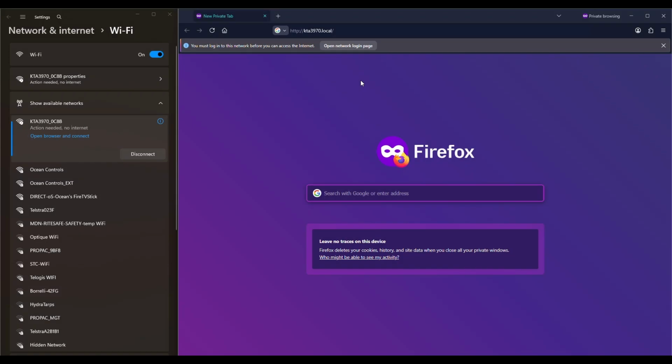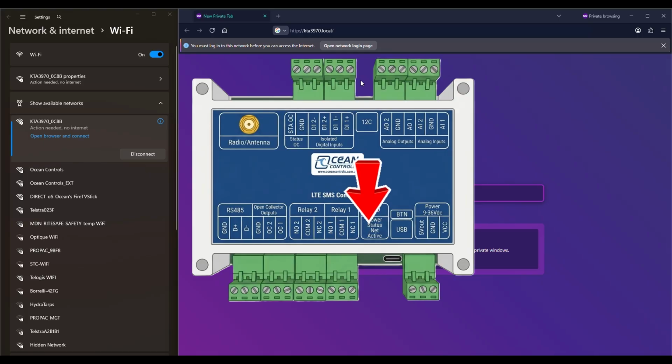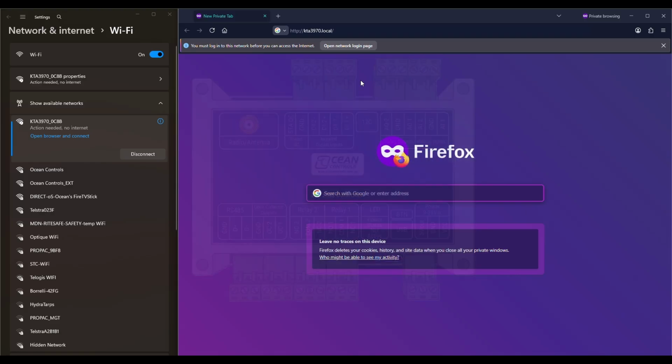To configure the device, we can use the locally hosted web page. To access the web page, hold down the button mounted on the PCB right next to the USB-C port for 3 seconds. You can release the button once you see 2 green LEDs. Once the blue LED is blinking slowly, the web page is hosted and we're ready to access.